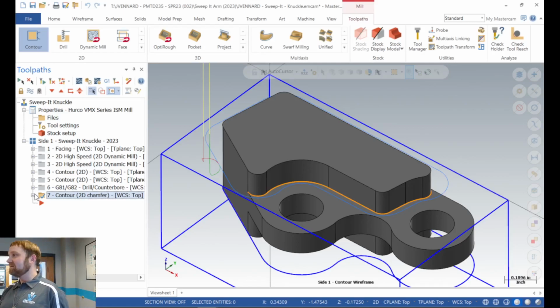That's why I want you to get used to those errors. For me, as soon as I hear that, I know we've got a work offset issue. It's never that the program's traveling 18 inches from where it's supposed to be. It's because we didn't get our origin set right or in the right spot.